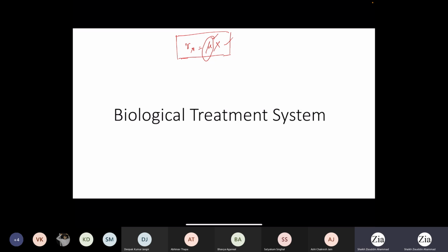So to avoid such incidents, there are strict regulatory norms for all bioprocess industries wherever they use recombinant strain. Before discharging any waste stream or any biomaterial, they have to ensure that the stream is actually not having any living recombinant cell.